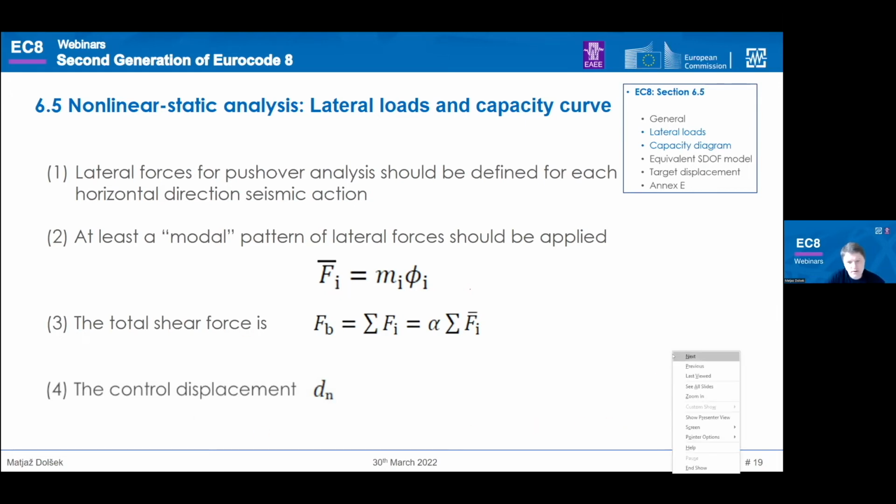Then it's also defined the control displacement. Of course, when you do the pushover analysis, you have to push it beyond the significant damage limit state. But you have to control the displacement at a given point of the building. For buildings, this is usually the center of mass, but it can be defined also in different points.